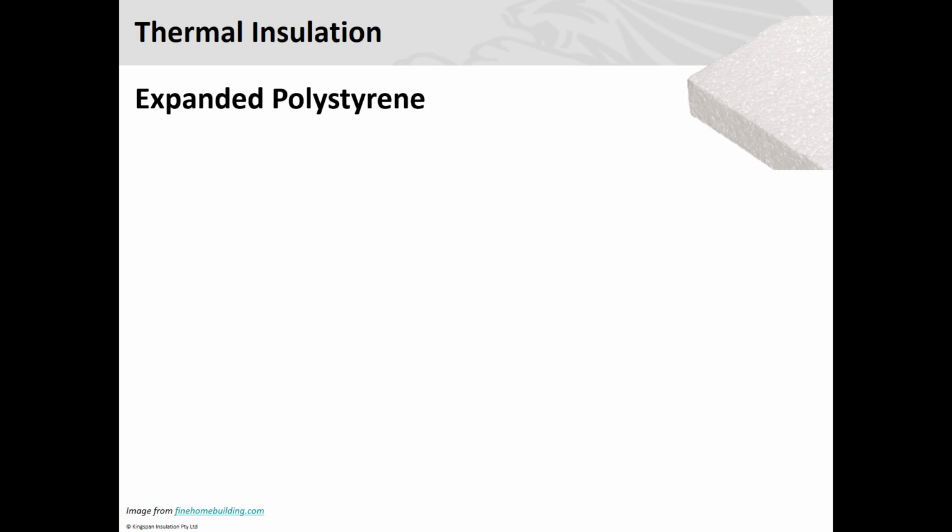And does it class as non-combustible? No, it's not classed as non-combustible. So you still need to be careful where it is being used. But it's not as flammable as polystyrene. You can basically put a blowtorch on it, and you won't get any sort of melting or distortion in the colour. You will get some charring, so the outside will char, but you're not going to get that melting or combustion. That being said, it's not classified as non-combustible, because that Australian standard is very hard to meet. It is, yeah. The 1530 part 1, it certainly is.